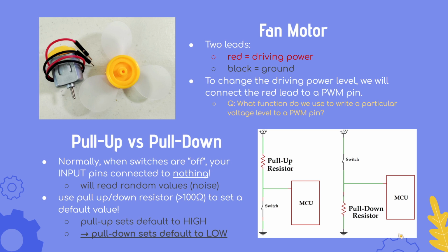No one? No one else? It's not digital, right? It is analog, right? Okay, very good. So you can't analog write from an analog pin because analog pins are only input on your Arduino pin, okay? But you can analog write from a PWM pin, right?